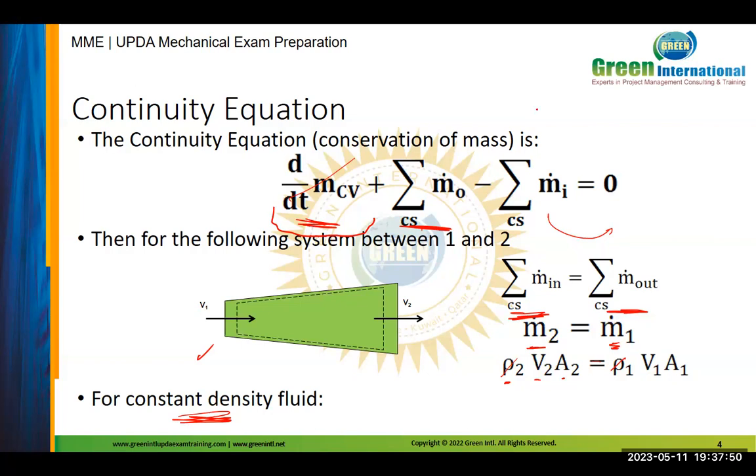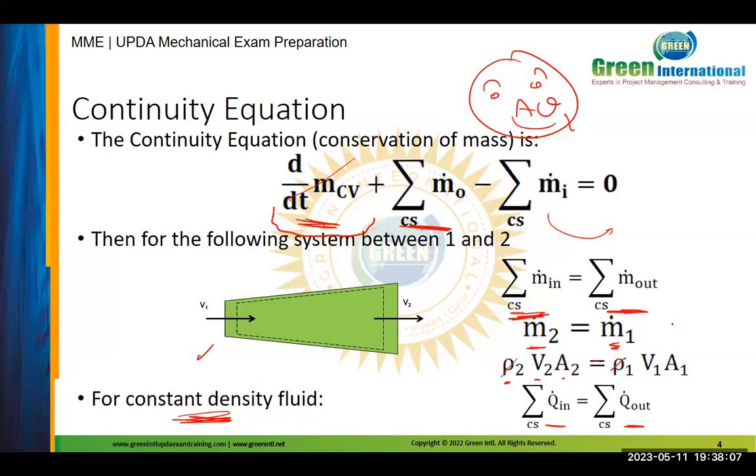The second important point for this slide is the units. They play a lot with you on the units. m dot, the mass flow rate, has units such as kilogram per whatever unit of time, which can be second, minute, hour, all accepted. In British units, it is slug per second, slug per minute, slug per hour, and also pound mass per second, per minute, per hour. But Q has a lot of types of units, like what?